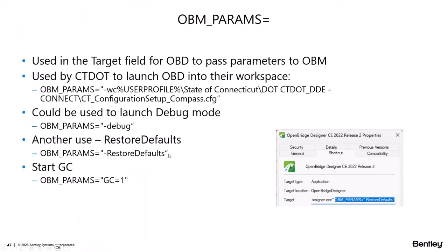If you're not familiar with that, go out and Google MicroStation restore defaults. When you launch a MicroStation-based product, the dash restore defaults tells it to go out there and clean up about 4 different folders that have a lot of temporary files in them for you very quickly. So really, really handy.